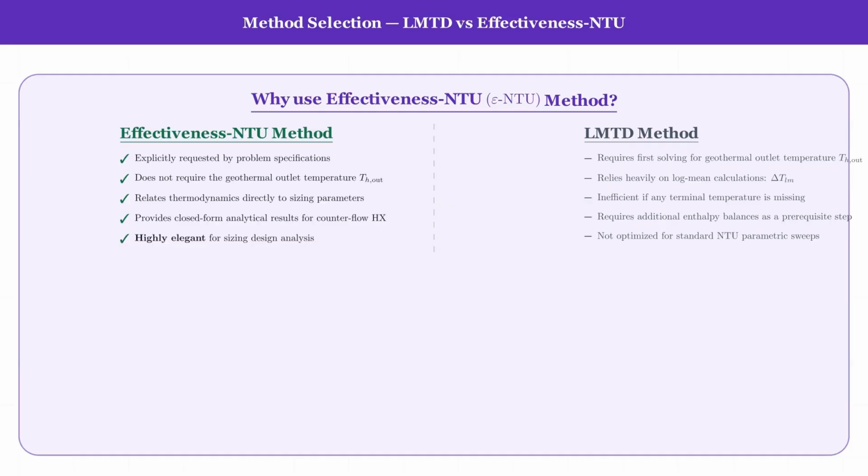Fourth, for a counterflow heat exchanger, the NTU method has a clean closed-form analytical expression relating effectiveness, NTU, and the capacity rate ratio. There is no iteration, no chart reading uncertainty, no approximation. A single equation delivers the NTU directly.